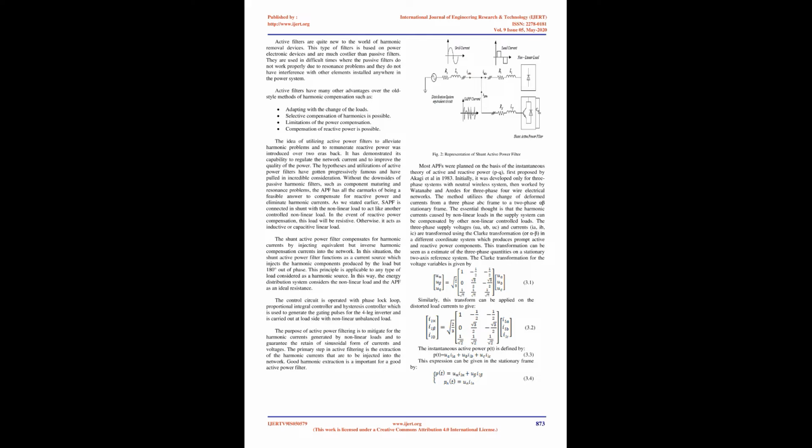Rotating machines. Harmonics increase dielectric losses in insulation, raise its hot spot temperature, cause premature failure, increase iron and copper losses and reduce the overall operational efficiencies. Fields produced by some harmonics, in the air gap, rotate in a reverse direction. This can cause cogging, crawling, or even shaft vibrations.